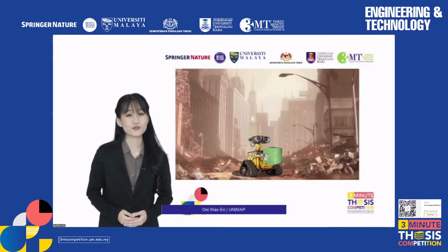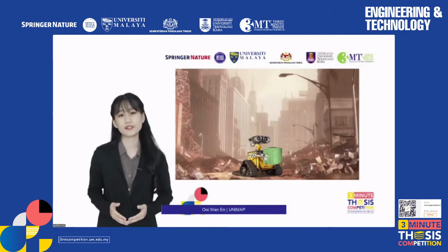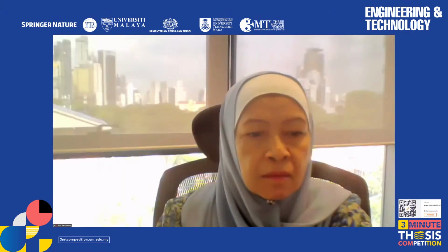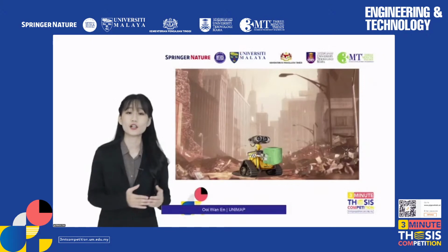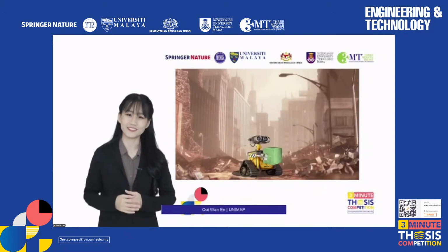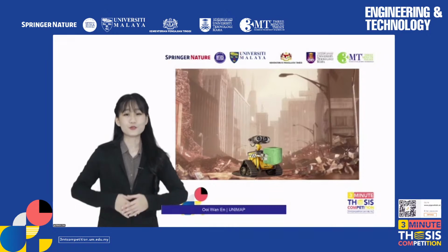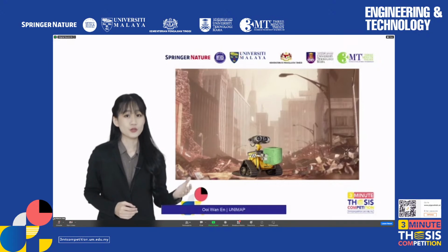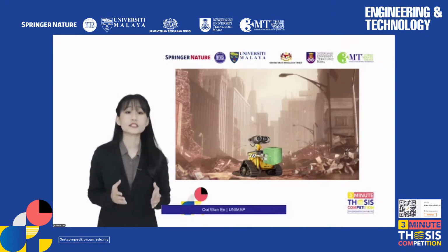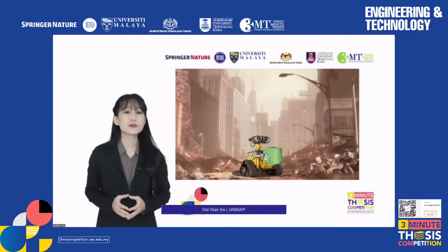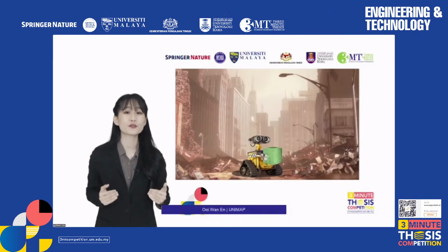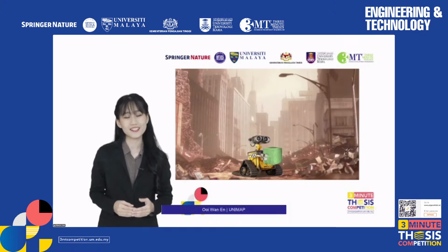To my knowledge, the byproducts from electric power plants, water treatment plants, or steel mills can be converted into 1 part geopolymer, which is essentially a green building material that can replace cement. 1 part refers to a dry mix of all the ingredients used to make geopolymer. Geo stands for earth, poly is many, and mer is parts. The preparation of this material produces 84% less carbon dioxide than the production of cement.